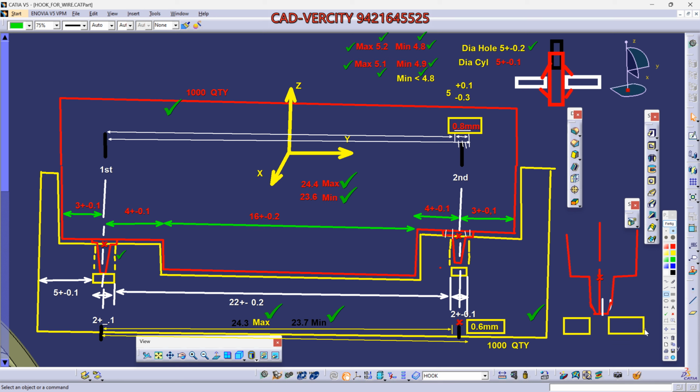Now, can you push your red part a little bit downward? Because of the entry chamfer it will align automatically. Otherwise you will need to apply force. Yes, sir. Okay, so this we call tolerance stack up.